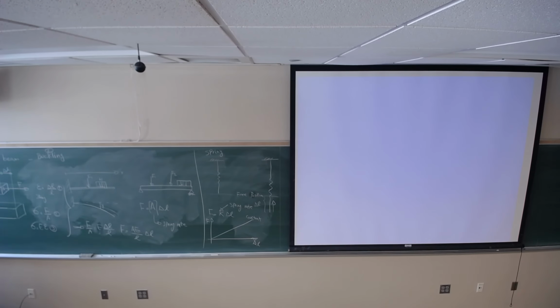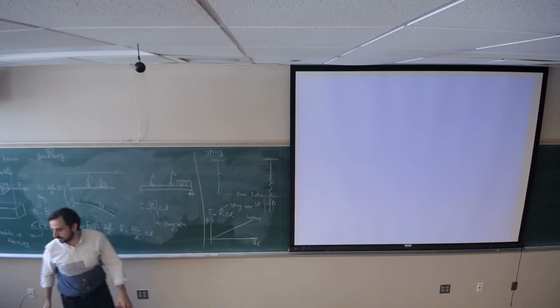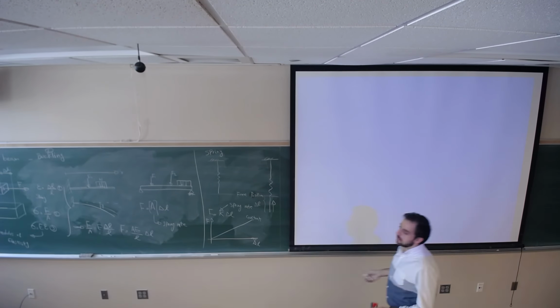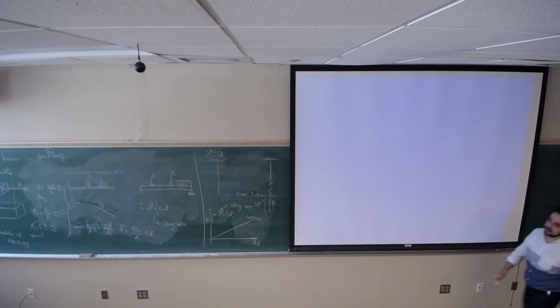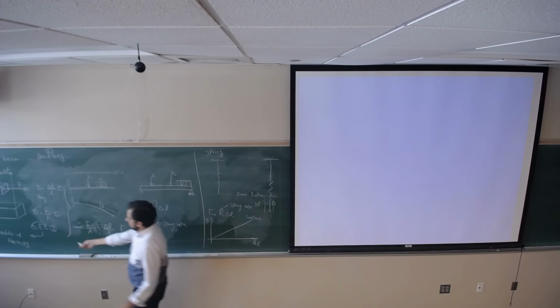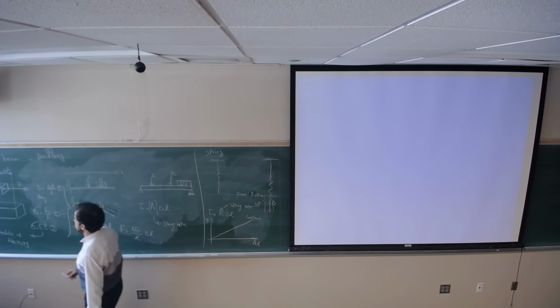What does the large E stand for? Large E. Modulus of elasticity. This is the correlation, the relation between stress and strain. Sigma equals E times strain. It depends on the material, so you can read it from the table depending on the type of the metal.